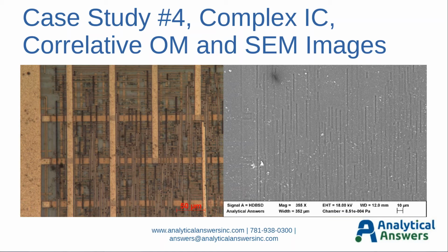And over here in the backscattered electron image, we can see that in this particular case, it's some residual encapsulated material that's left behind. But if it were an anomaly, such as an ESD anomaly, it would often look like a lightning strike happened here, and we'd see a hole and maybe some melted material, etc.